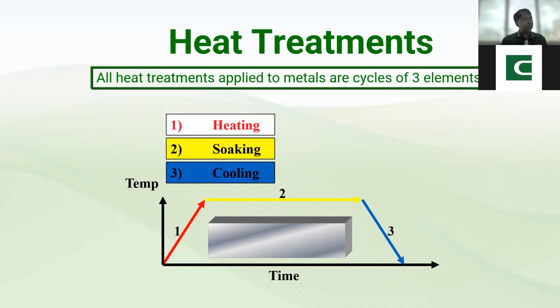Ang aking sagot dito sa susunod na topic natin, the different heat treatment. Okay, sir. So, pwede, sir. Pwedeng maging brittle ang material. Depende yan sa heat treatment. Meron tayong 3 parts of heat treatment. First is the heating rate. This one, the number 1 is your heating rate. Mabagal, slow heating, then soaking time and soaking temperature, depende sa material.